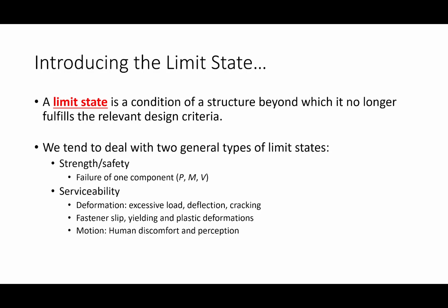I'll give you an example of a service limit state. I'm going to use beams as well. So there's going to be beams up here that are supporting the floor from upstairs. And I can think of two limit states, at least, that those beams are going to have to withstand, or going to have to meet. One of them is strength, right? The beam has to be strong enough so that the load doesn't fall down and kill people. But another is a limit on deflection.